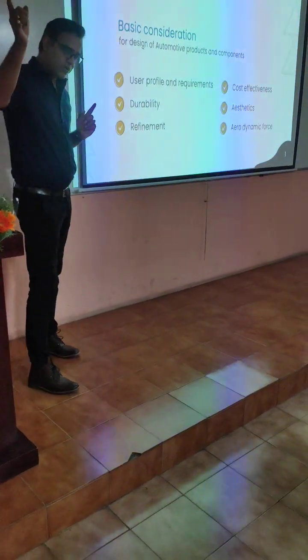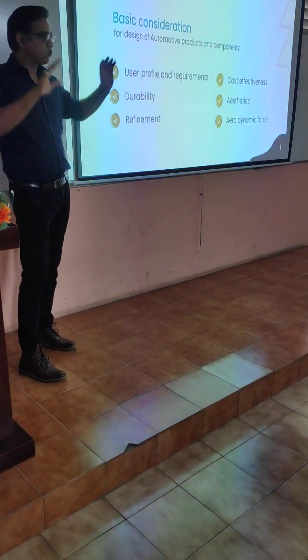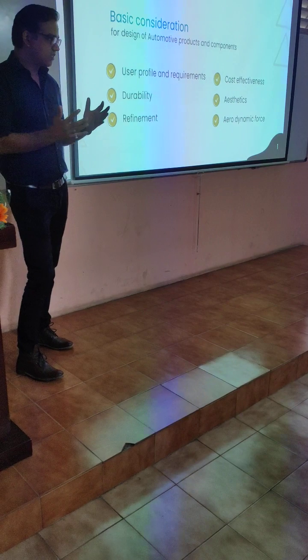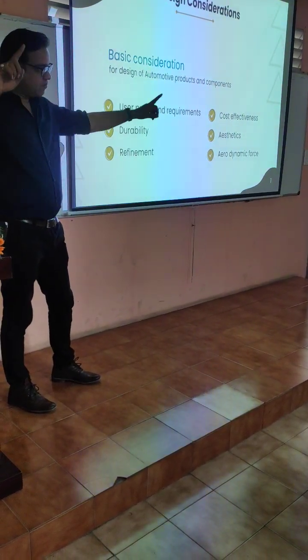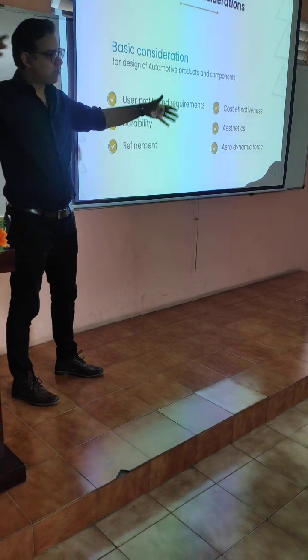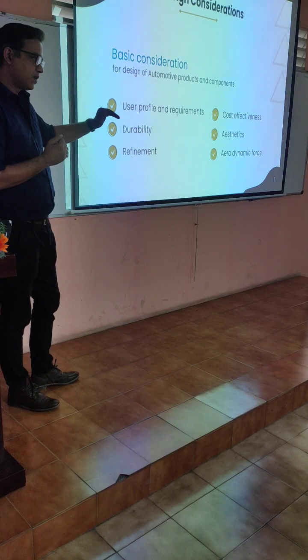But when you look at the stack, from the front of the vehicle to the back, so many plastics, so many panels coming and joining together, those minor rattles will end up becoming a major rattle when you look at the full vehicle. And that is why it is important that you damp everywhere.